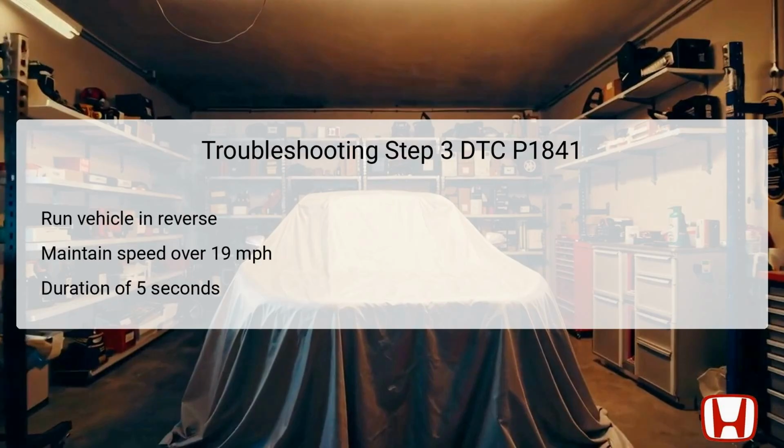The third step involves running the vehicle in reverse mode, while ensuring it reaches a speed of over 19 miles per hour, 30 kilometers per hour, for at least 5 seconds. This is necessary to apply real-time conditions to the diagnostic assessment.